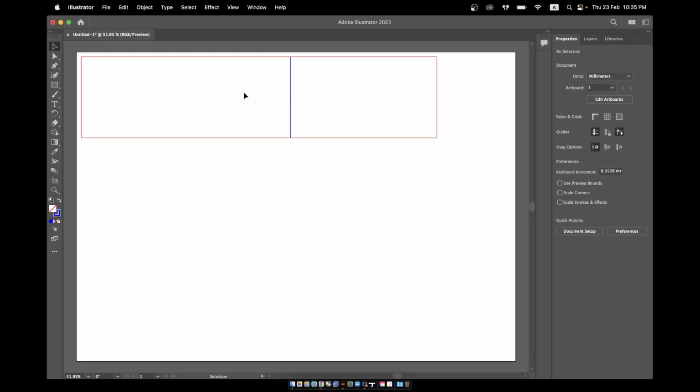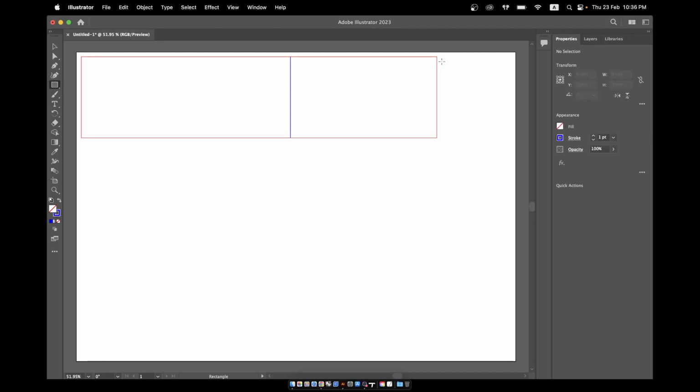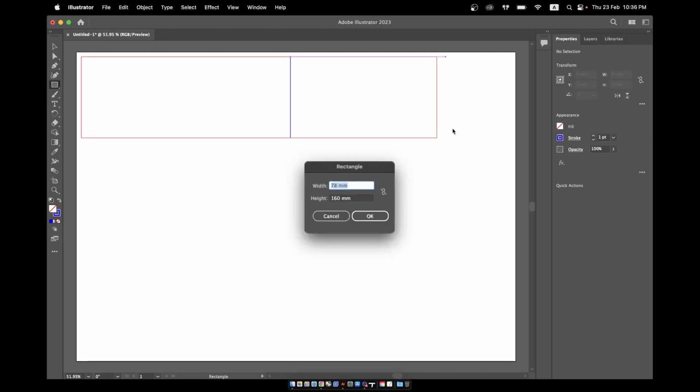Of course, remember you have additional pieces that you're going to insert to the upper side. So now we're going to draft the attachment. You will use the same rectangle. Width, we're going to set to 30, or maybe just set 40 mm.